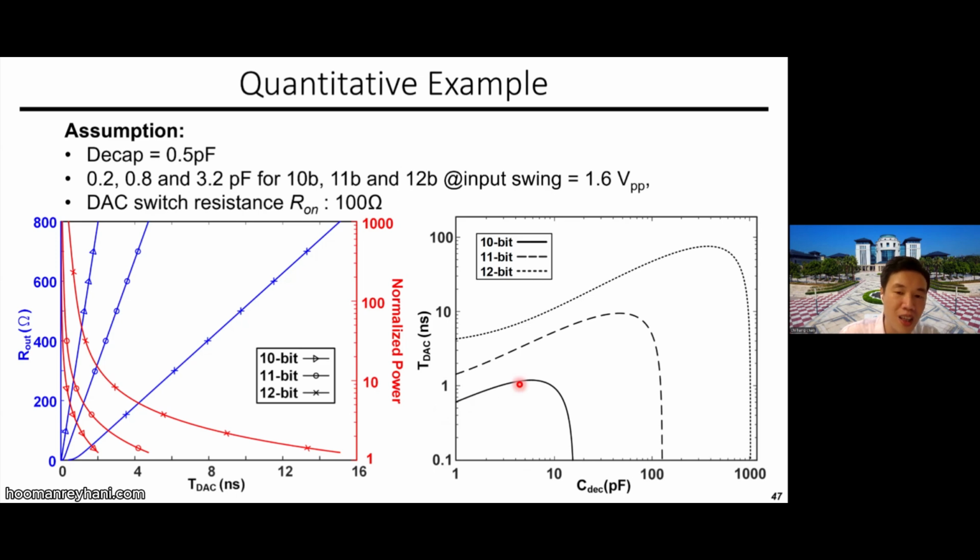All right. The intuitive reason for that is because at this value of decoupling capacitance, it does not give enough decoupling effect to suppress the ripple. The ripple is still there, and now you add a load on the reference voltage.